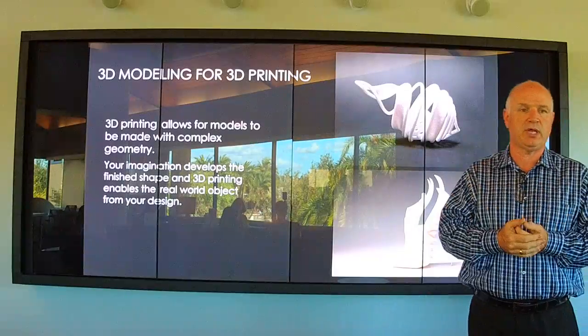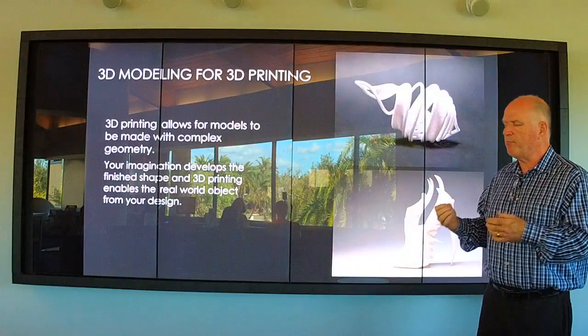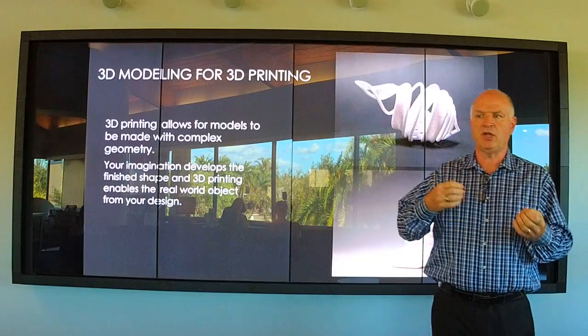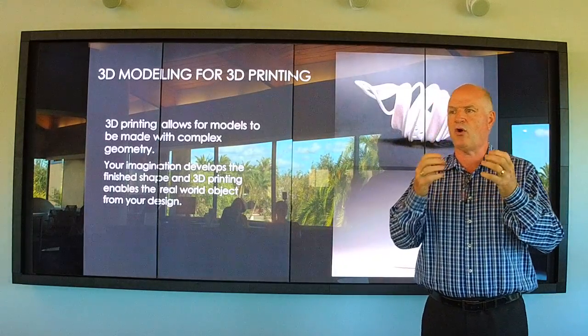We do a lot of 3D printing here at the university, and students are actually learning different techniques on how to model for 3D printing, how to get the best system. The other thing when you model for 3D printing is it's not just the plastic. While it's printing, you can have pauses and things like that, where you can put in nut traps or metal bars or electronics. You can actually put them directly in the print and have the printer pause at a certain level to be able to put that in.